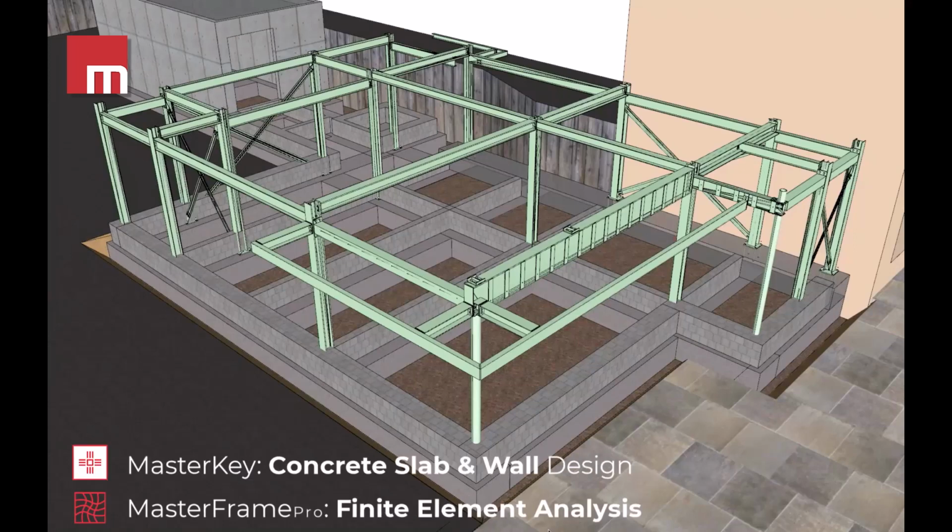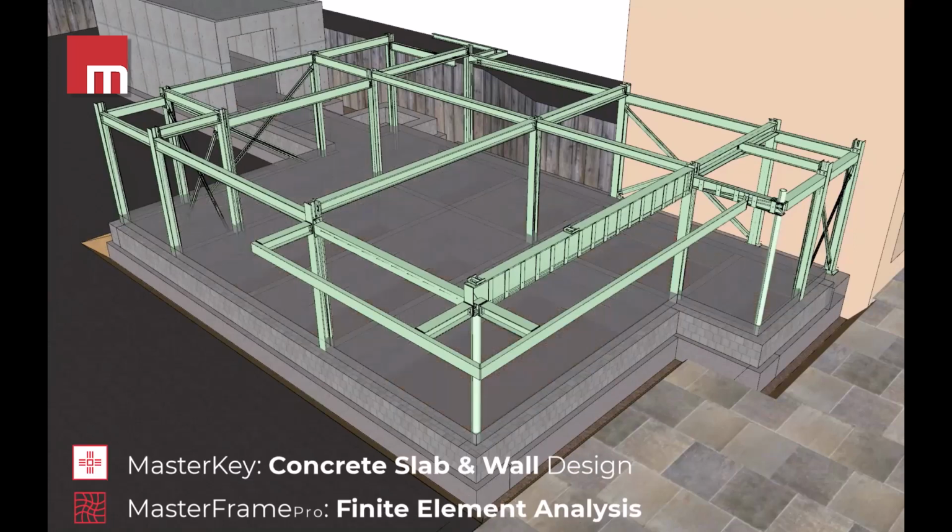The ground slab can be modelled again in MasterFrame, and the ground floor slab in this building is a suspended in situ slab cast on top of blockwork riser walls, as we can see. And for the purposes of this presentation, we have included it in the MasterSeries. I'll show you an example of that in the MasterSeries model, but in reality, ADD modelled the FE surface separately from the main model for a few reasons.